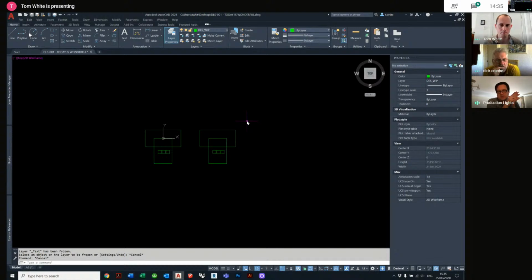I think also it's worth noting the transparencies, and Dick, to answer your question, if you receive a big plan and there's hatches all over it, if you can get them all on one layer, what you can also do is give a layer of transparency as well. So you could get all your hatches on one layer, and instead of having to do a transparency on all of them, you can just apply a transparency to that entire layer, knock that layer back, so you can still see what's going on, but you've still got the information the hatch is there.